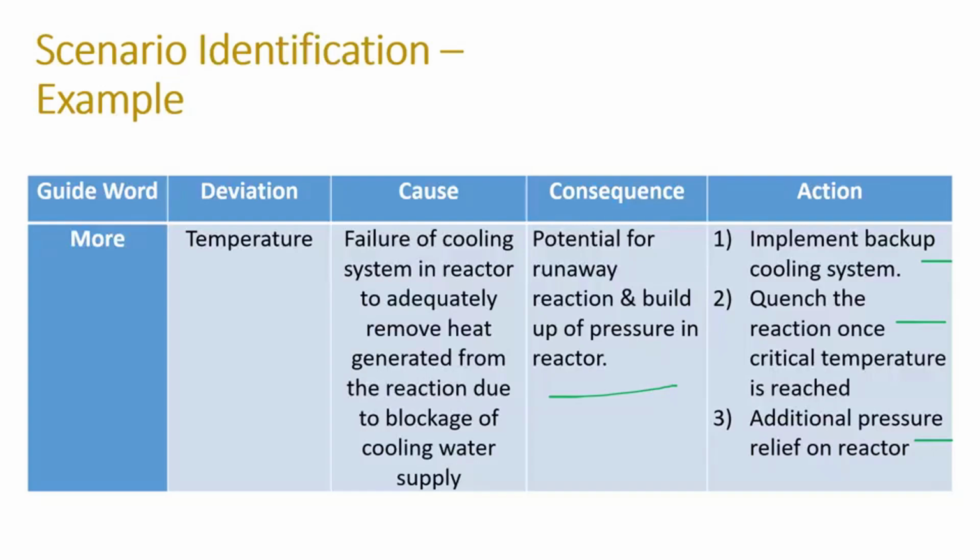So again, here's where we could identify some scenarios. Now, the worst case scenario is the one that requires the largest relief area, which for this example, of course, this would be it. But here's, again, an example of a tool we can use to identify scenarios. We can start to look at making calculations for that relief area, and we'll see that a little bit later on in the determine step.